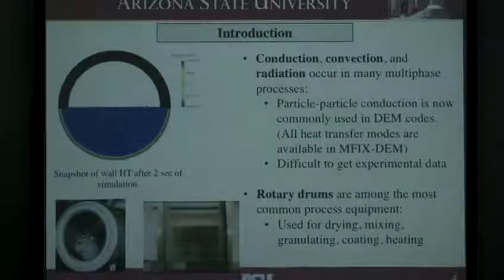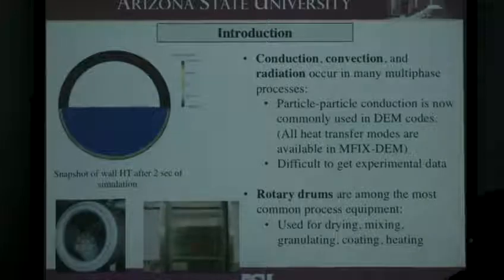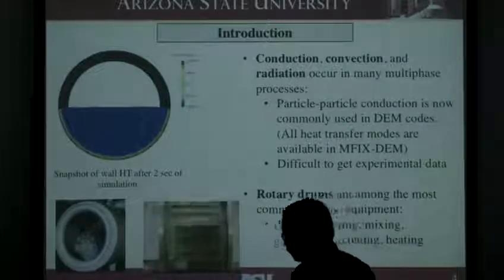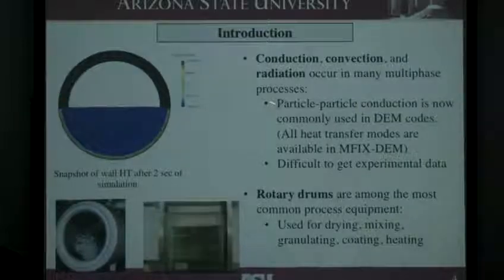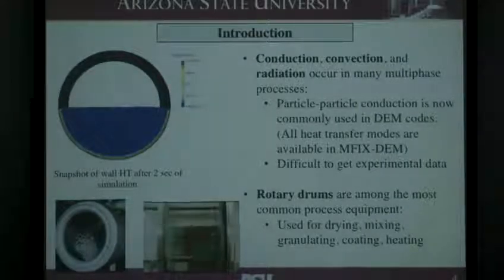So conduction, convection, radiation, heat transfer occur in so many different multi-phase processes. And there's a couple different approaches to looking at these. So if we look at simulations, we now have seen particle-particle conduction to be pretty common in DEM codes. So I'm actually going to focus very much on the granular phase.